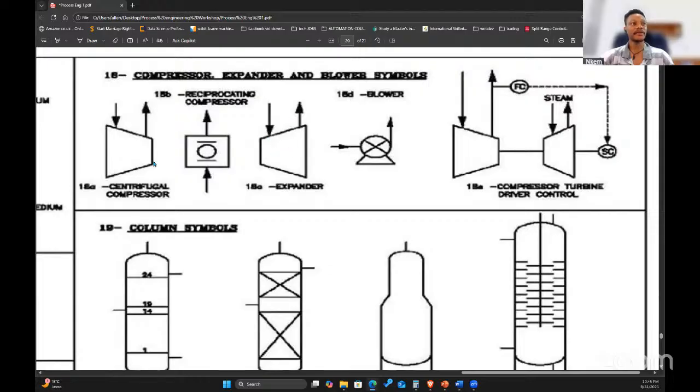Cooling takes effect. Here, temperature will be high. So in this case, let's say for example, you have an equipment, downstream of this equipment, you're going to have a cooler here because the temperature will be very high. So depending on what you want to achieve, you have a cooler at the downstream of the compressor to cool down the temperature. Because the idea of the compressor is that you only want to increase the pressure, right? But you don't want high temperature. So for you to handle high temperature, what you need to do is to have a cooler downstream of this. So use a cooler, reduce the temperature, but the pressure doesn't reduce that much.